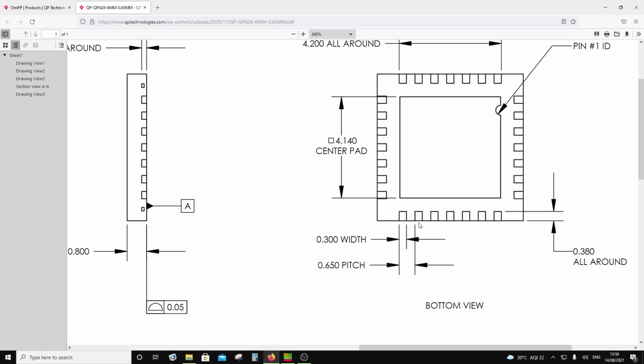Okay, why is it important? Well, this is going to be the capacitance between the pins. So what I'm going to do is at 0.3 I will start, and then at 0.83 I'll start that. So let's go ahead and draw these pins.